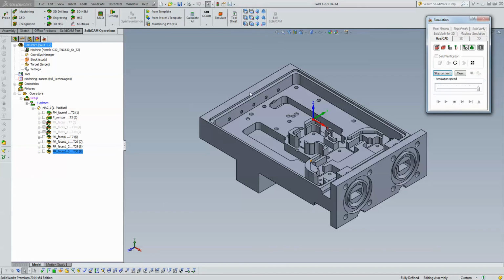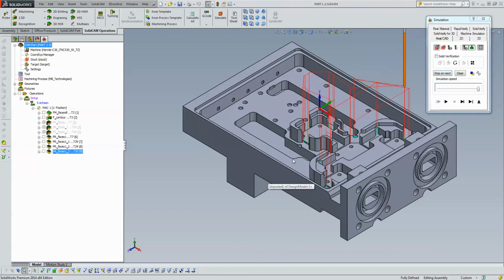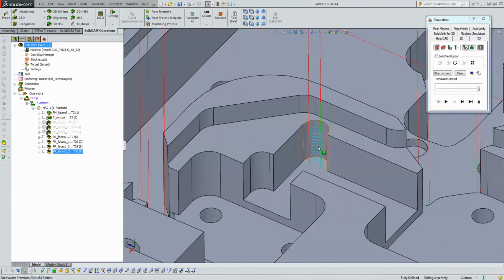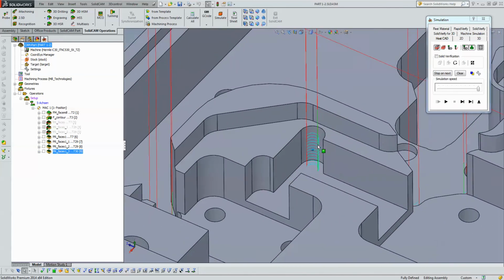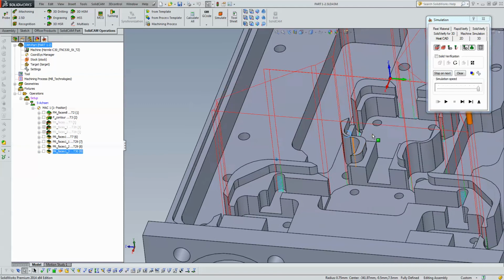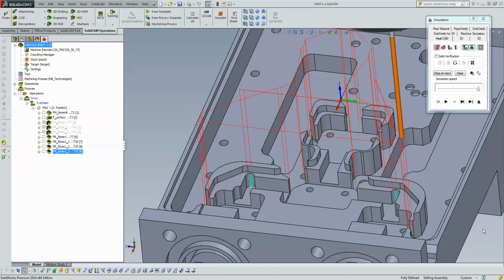you'll see that the tool path is exactly only in the areas where it is needed. Take a look at this area over here. You see it worked exactly in those areas as well. This area over here may have needed even a smaller end mill, so I can use even a smaller end mill over there as well, if needed. And I can go down further and further, but note, picking the geometries in this particular case was simple. I only picked it once, and I just went down every single time to a different end mill, and actually finishing off the part this way.